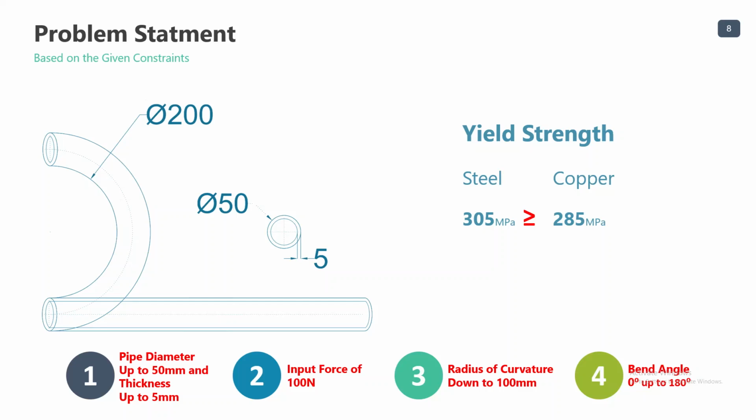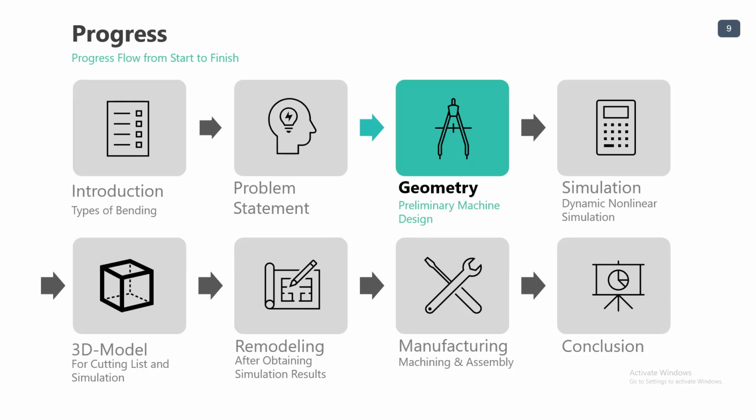As shown in the tables, after comparing the yield strength of both materials we deduced that carbon steel had a higher yield strength, thus a higher force is needed to reach the same constraints. So, we based our future simulations on steel. After making sure that the 3-roller bending type of machine can reach the desired constraint, it was approved, and we proceeded to the basic machine geometry.